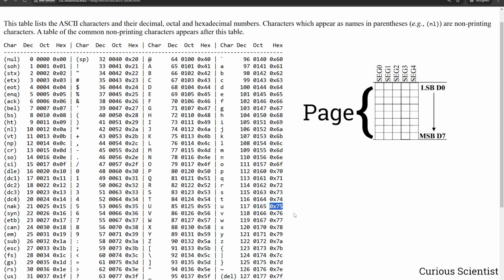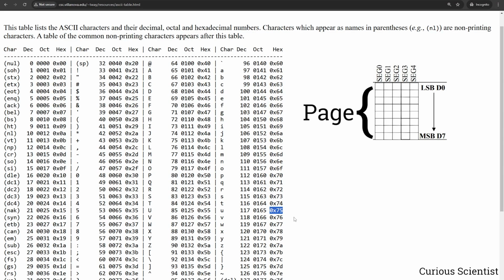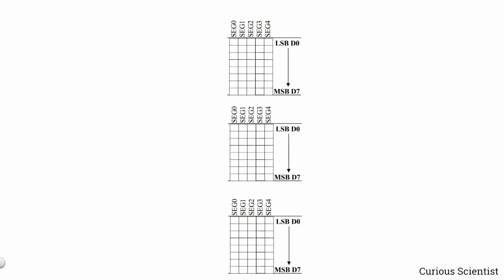And then we can build a, let's call it vector or an array for each character, which consists of 5 bytes. So each byte is the 8 pixels within a segment, and then we have 5 of these because one character is built up by 5 segments. So let me bring up a drawing software and let me show you how we can draw actual characters. I copied this segment illustration from the datasheet because this will come very handy when I try to show you how the segments work and how the characters work.